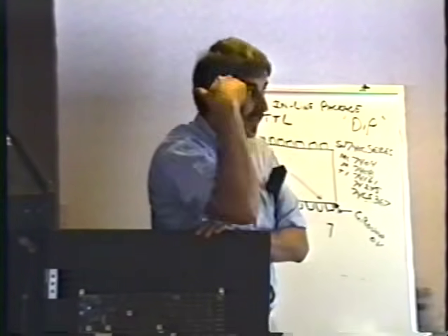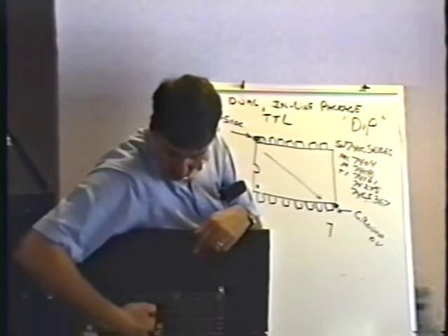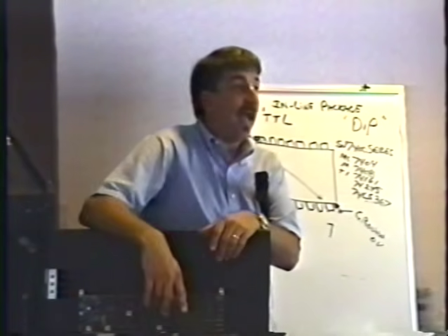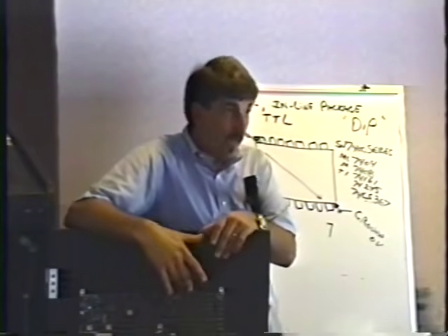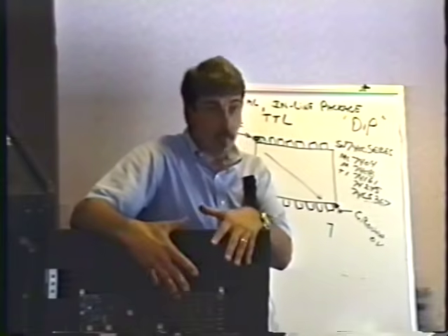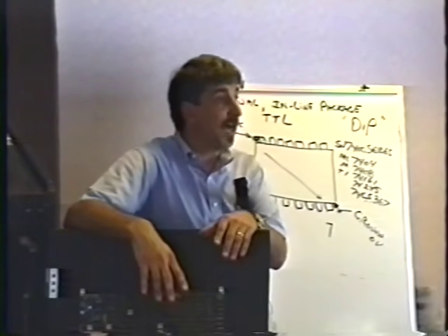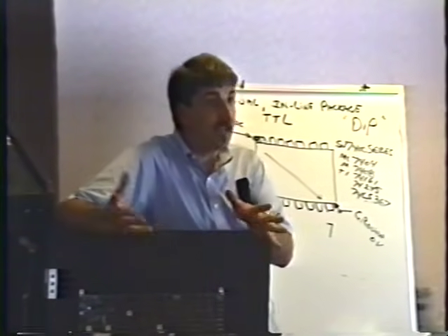So you don't have to know anything about electronics to do that, do you? You just have to start swapping the chips. Make sure you swap the correct one. Have the exact same board, swap them one for one. And if you find that you have a bad part, then you can call up your distributor, and you have to get these from your distributor, and order the replacement ROM or replacement part, whatever it is. I've fixed tons of boards that way. Tons of boards. And again, that doesn't take any intelligence at all. You just have to sit down and do it.